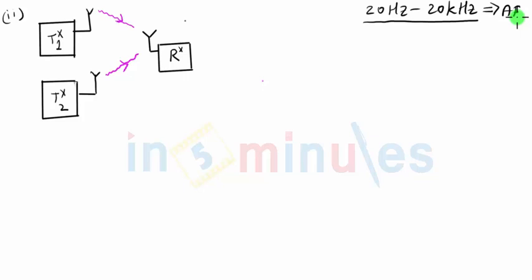Now it is very obvious that in any practical system there will be multiple transmitters. For example, we have multiple radio stations. At any given point of time, my receiver is only connected to one radio station. Now, how can I connect the receiver to one radio station? Every receiver has a bandpass filter on its input side. Every bandpass filter has something called a passband. The filter allows only the frequencies which fall in the passband to enter into the circuit. So the receiver will receive only those frequencies which fall into the passband of the bandpass filter on the input of the receiver. This is called tuning of the receiver.